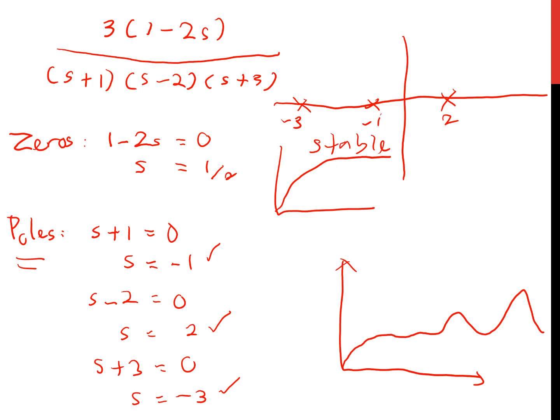So first it becomes steady because of the pole, but in the end it becomes unsteady. Although you have one pole at the unstable region, in the end your process becomes unstable. We don't have any partially stable; it is either stable or unstable. It does not matter if you have 4 or 5 poles at the negative region, as long as you have one at the unstable region, then in the end your process becomes unstable.